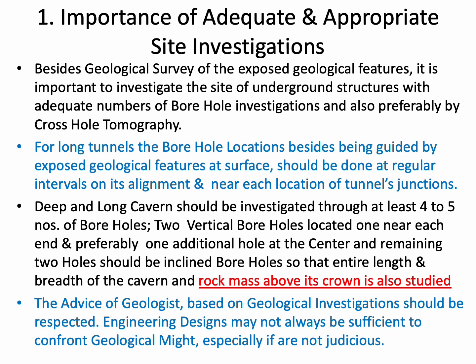Deep and long caverns should be investigated through at least 4 to 5 boreholes: 2 vertical boreholes located one near each end and preferably one additional hole at the center, and the remaining 2 holes should be inclined boreholes so that the entire length and breadth of the cavern and the rock mass above its crown is also studied. The advice of geologists based on geological investigation should be respected. Engineering designs may not always be sufficient to confront geological might, especially if they are not judicious.